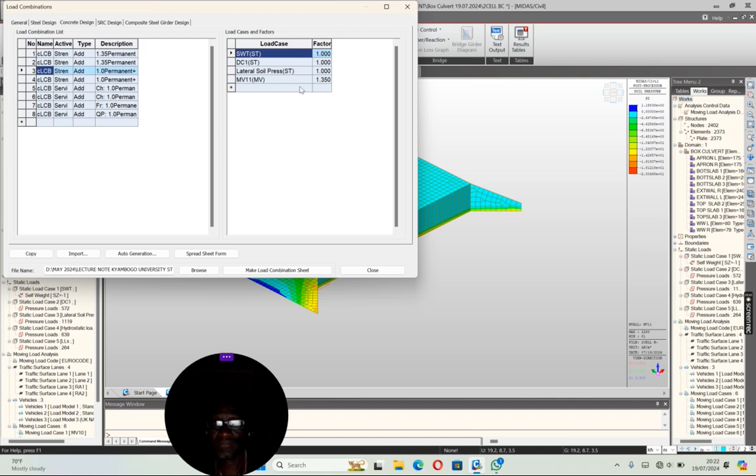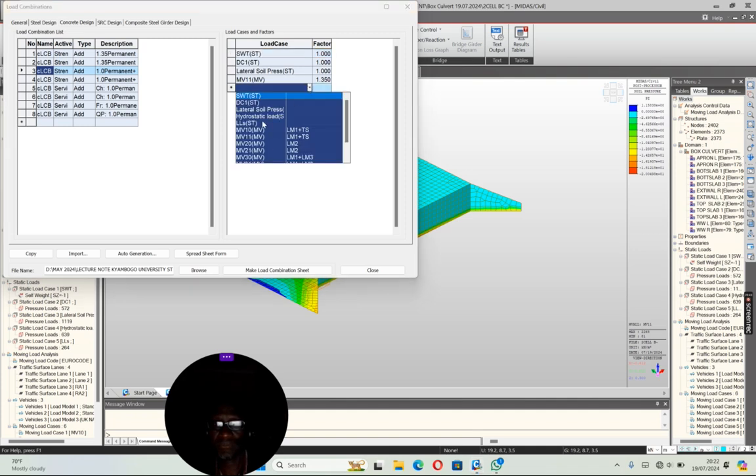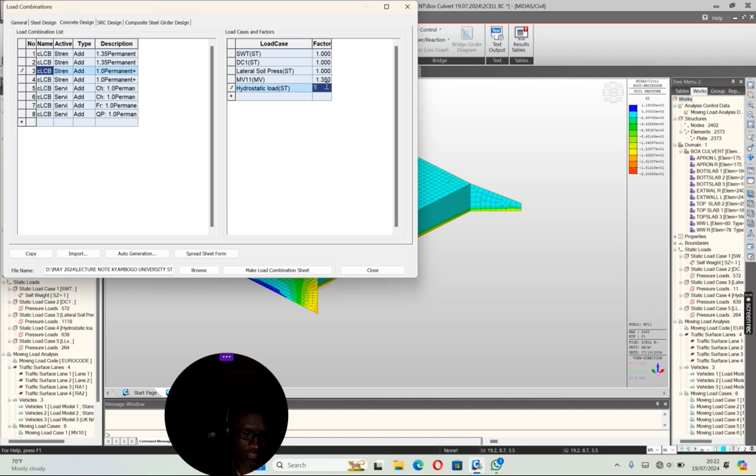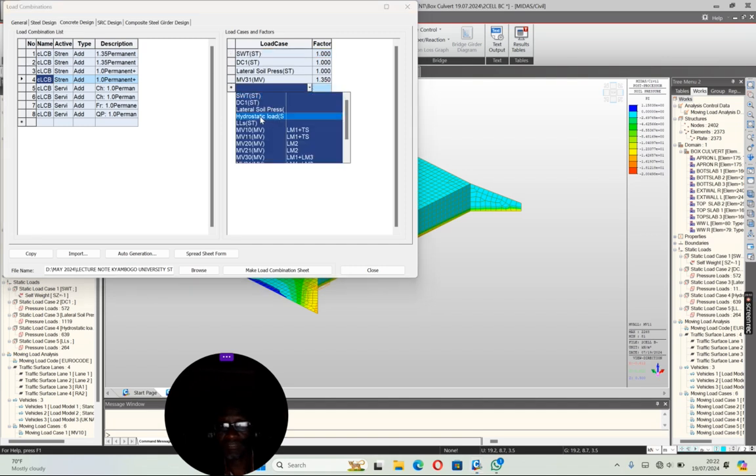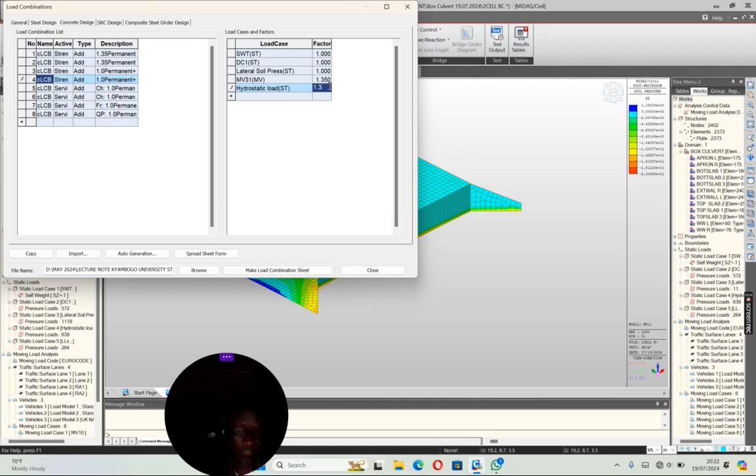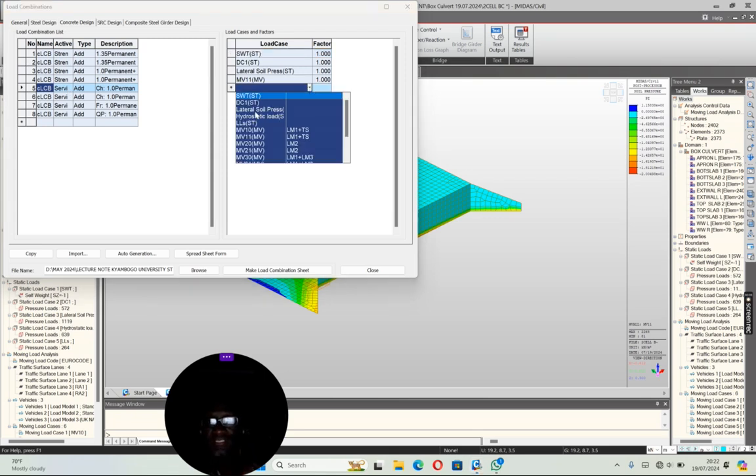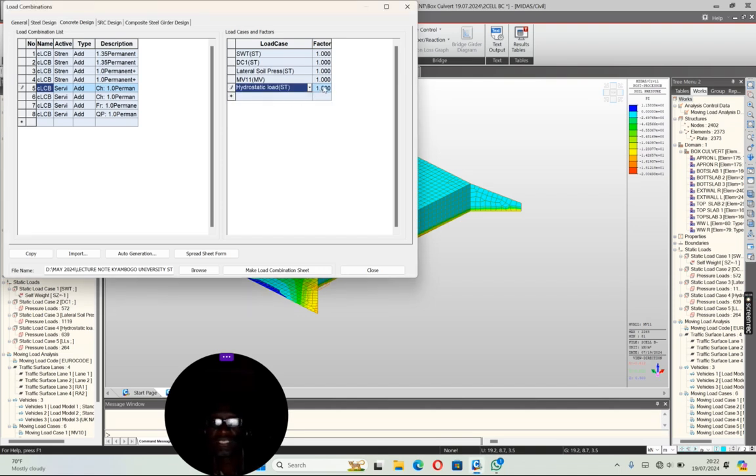And then I do that. I'll put 1.35 for our demonstration. Lateral soil, that one is missing out. Okay, 1.5. I will do mine, but you guys can now check the code. You throw in the comments, say this is what you found, because sometimes politics affects us. We are running up and down, and you find you are not seeing some of the things. And okay, hydrostatic here. Okay, we leave it now as 1 for serviceability.